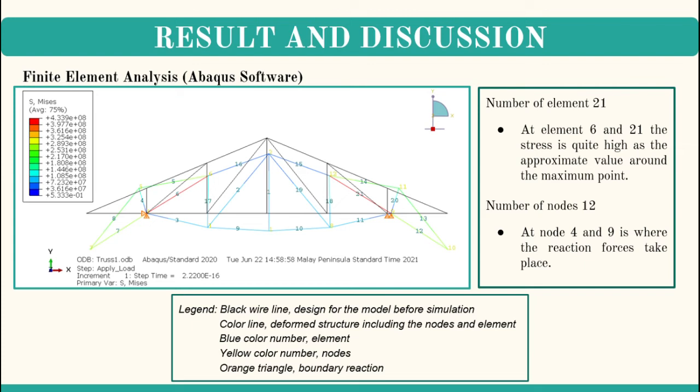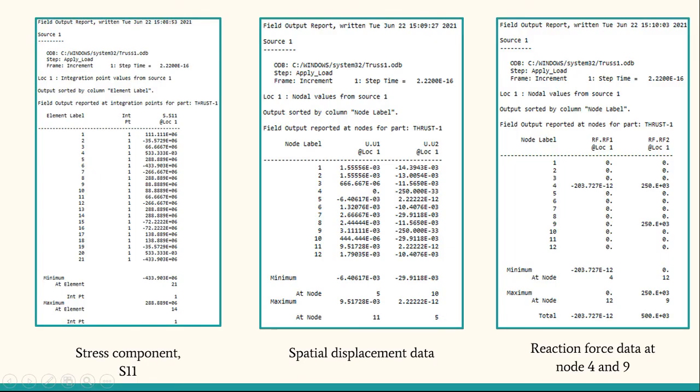As for the reaction force, there is no change with the fixed boundaries, and there is a slight change to the right of the x-axis, which was the roller. As for the deformation scale factor, we use the standard one, and the maximum stress is around 433 megapascal. We will obtain the result of the stress component S11, the spatial displacement data, and the reaction force data.